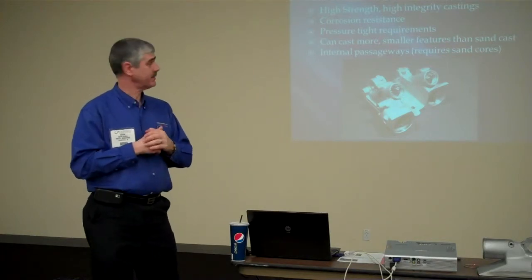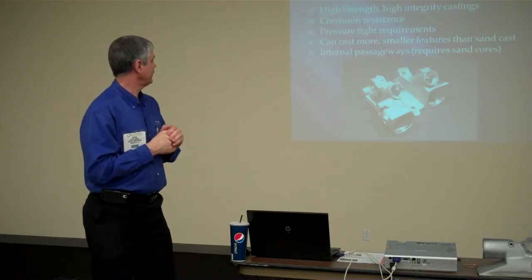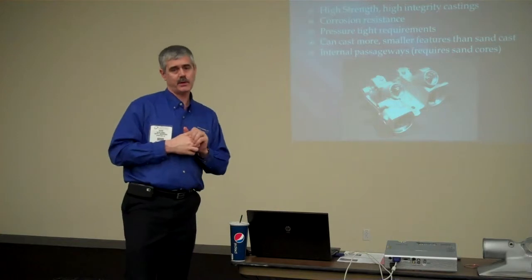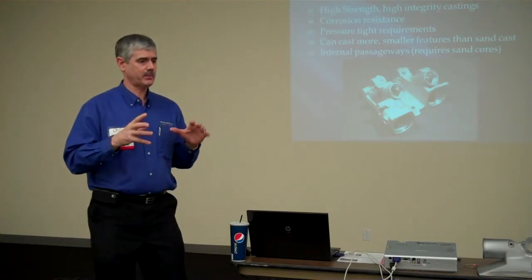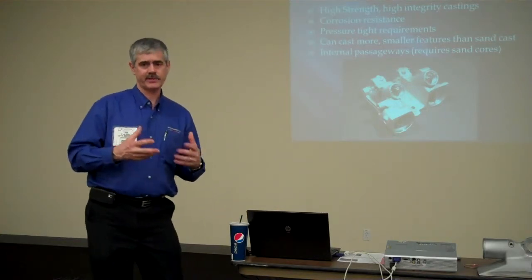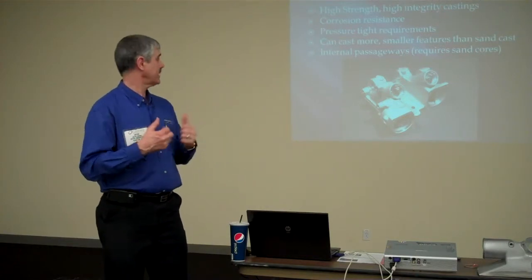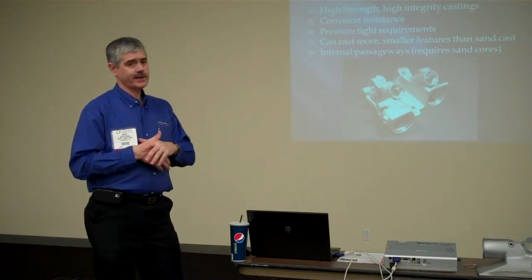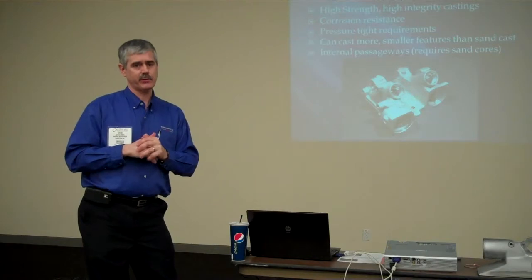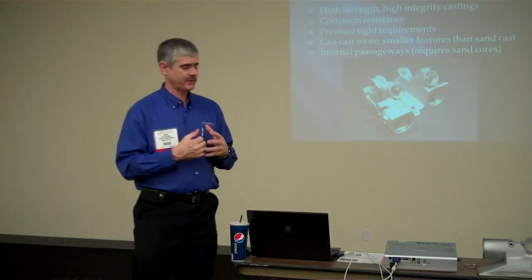There may be design-dependent reasons for specifying permanent mold. High strength, and that's again where there may be some important aspect of the part's application that means it can't be sand cast or can't be die cast. High strength and high integrity. By high integrity, I mean that it's got uniform properties throughout the entire section of the part.